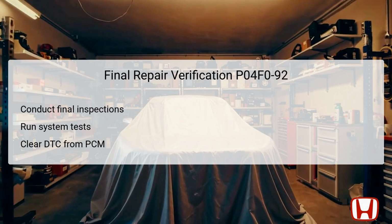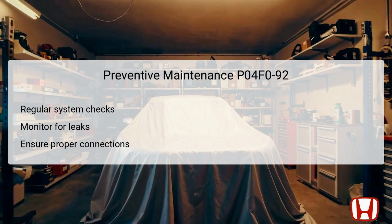It is important to monitor the vehicle post-repair, ensuring no further trouble codes emerge, which would indicate that the resolution is effective and lasting. To avoid recurrence of DTC P04F0-92, implementing preventive maintenance is advisable. Regular system checks should be scheduled, including inspections of the EVAP canister, purge valves, and associated components for any potential issues.